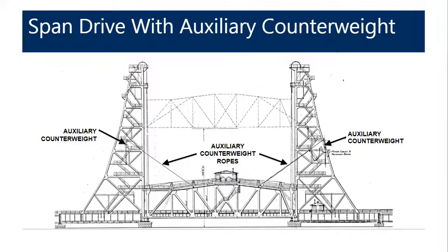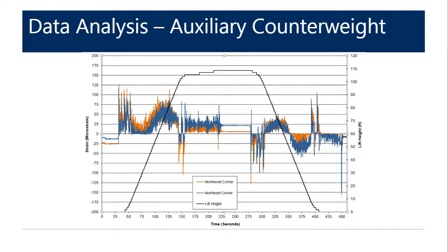Now, as I touched upon, the behavior of that fundamental balance equation is sinusoidal. And here you can see the strip chart for this tower drive vertical lift bridge with an auxiliary counterweight. And you can see that the behavior of the operation clearly follows a sine wave, and that is the fundamental balance equation for this specific auxiliary counterweight system.